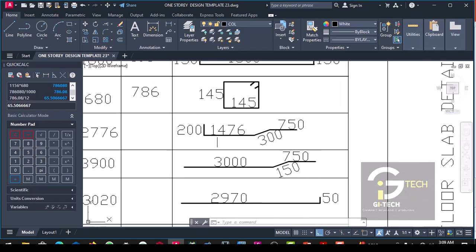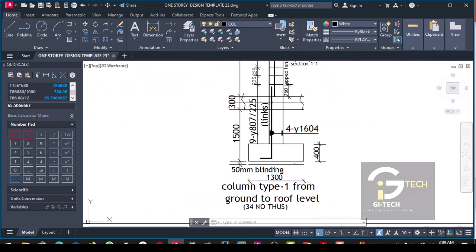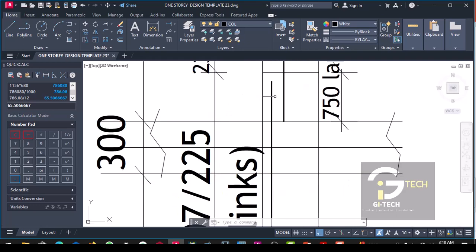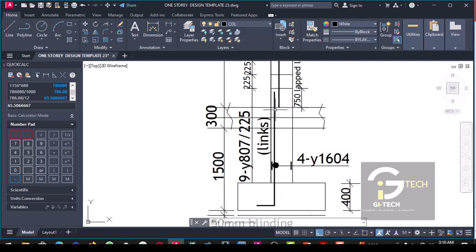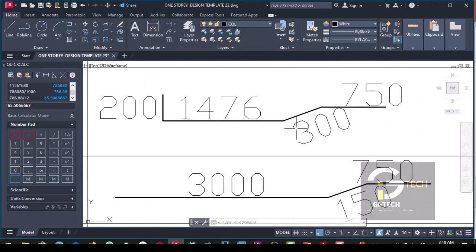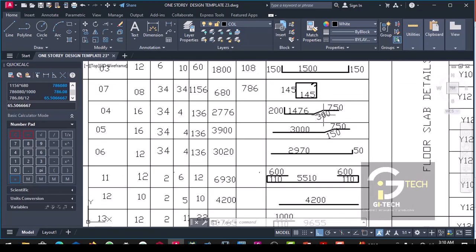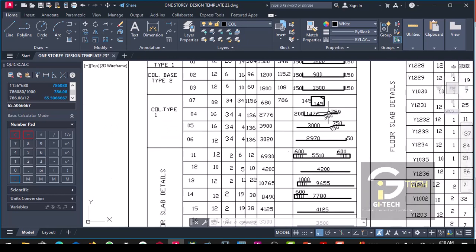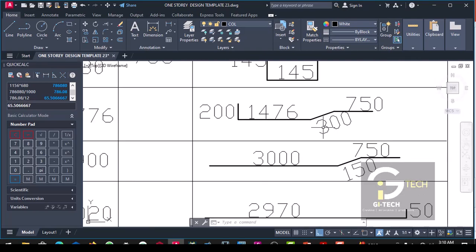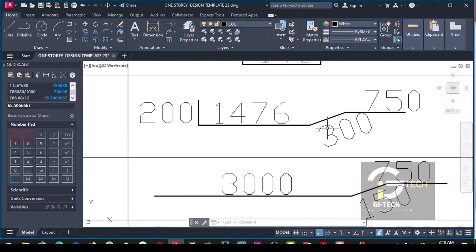So we want to calculate the shape of this. Now practically, this starter bar is always straight, except in a very rare occasion where you have to bend it the way it is. But the reason why we present this shape as it is, is to enable us calculate accurately the length of this bar.